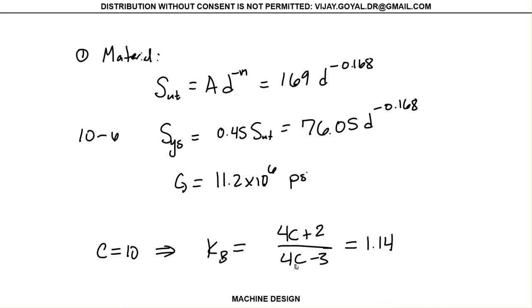And note that if your C becomes very, very small, less than or equal to 1, your stresses become higher. The reason they become higher is because stress concentration increases at the coils. That's why a small spring index is not acceptable either.